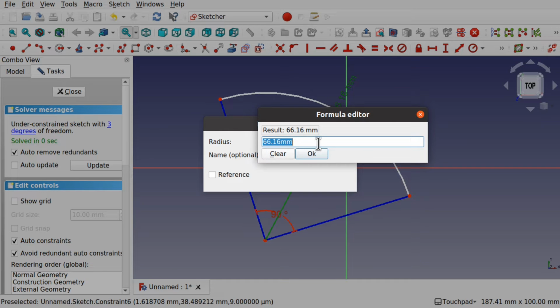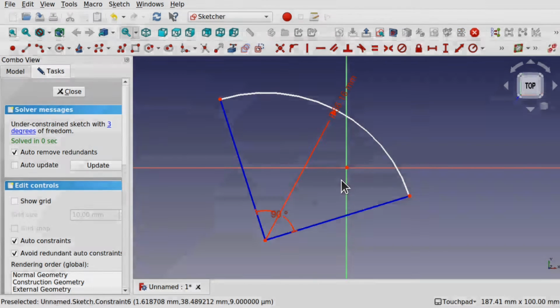icon on the end. Now we're in the sketch. I don't need to actually reference the sketch, so I don't need to do sketch dot, because we've got constraints in here that will actually be removed. Because if we're actually inside the sketch, we look at the constraints inside the sketch. Dot angle, the one that I've created, then we get a unit mismatch between results and required. So we can't actually use this. Even if we try some trickery like dividing it, times it, etc., we can't actually use that. So I'm going to clear that and hit OK.